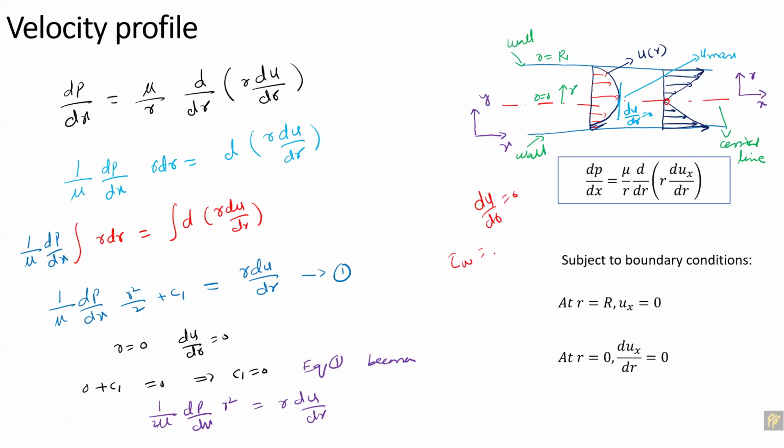So the wall shear stress formula is the viscosity and du by dr. Okay. So at the maximum velocity point, the wall shear stress is 0, because the velocity gradient is 0. So wall shear stress will be 0 at the center. At the wall, because the gradient is infinite, we have the maximum wall shear stress on the wall over here. Okay. So if you draw the wall shear stress, it will be drawn in this way, 0 at the center, but it changes linearly, like here.